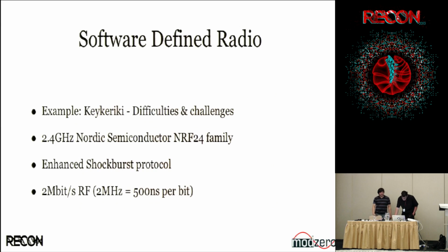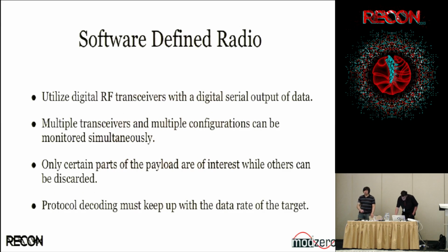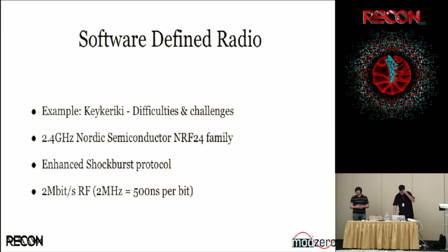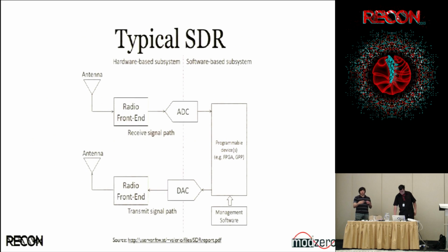The main idea here is you want to do this all in real time. There are lots of very basic operations that need to happen simultaneously. You need to match bits, and in hardware, this is just a matter of generating a gate which is large enough to match the bits against a certain mask. So the FPGA can literally do all the things that an ARM can do in 50 clock cycles, basically in a single clock cycle. And it's much more efficient to implement them in this fashion.